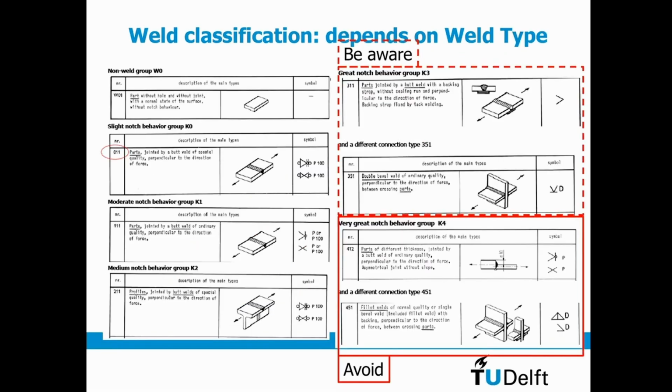Okay, so again, how does that result? You have classifications on the welding. I skipped the welding a bit, so this is no weld. This is a perfect weld with grinding, as you can see. This is a standard weld, just welded, no grinding.